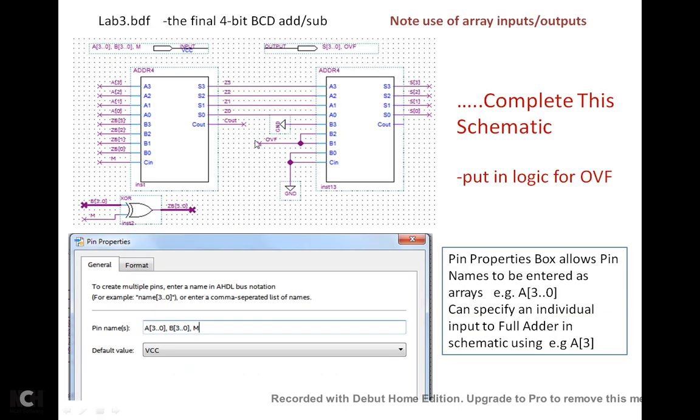One is it sets the two inner bits on the B side here to 1s when needed. Okay, so this B3 will be a ground. This B0 and this C and they're going to be ground. We're not using those. Okay, but we add 6 when needed by putting a 1 on overflow and setting the B2, B1 to 1. Okay, so that's that overflow circuitry.